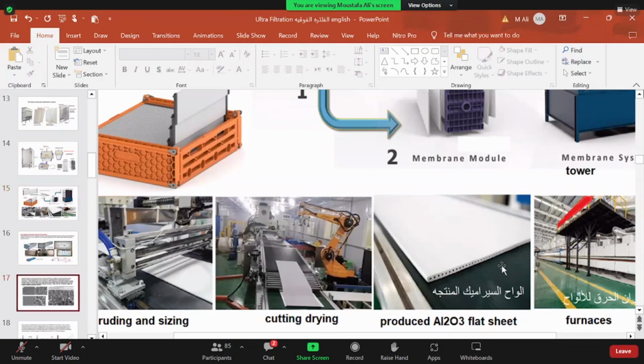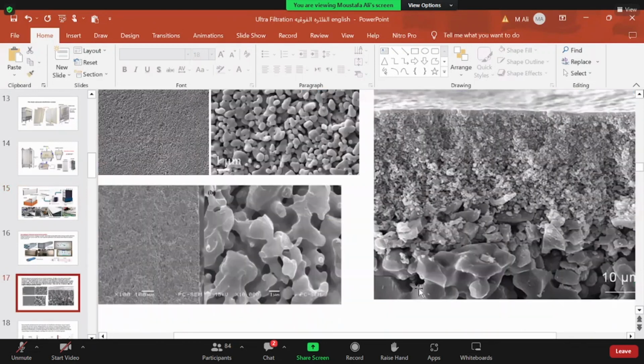Let's see what happens. We have the coarse material layer, the basic layer of the ceramic material, from 10 to 50 micron. This is the coarse side. This 1 micron is the fine part here. So these coarse particles go inside the furnace, not to have complete fusion, but what we define as incipient melting.